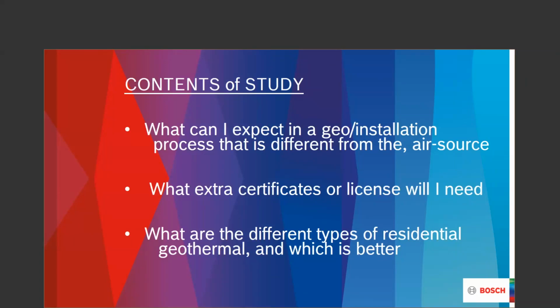But when we look at the COPs of an air source system versus a geothermal system, we see that with an air source system, as the wintertime pushes in and the temperatures outside fall, so do those COPs. My geothermal system sitting at my house does not necessarily care about the outdoor temperature.